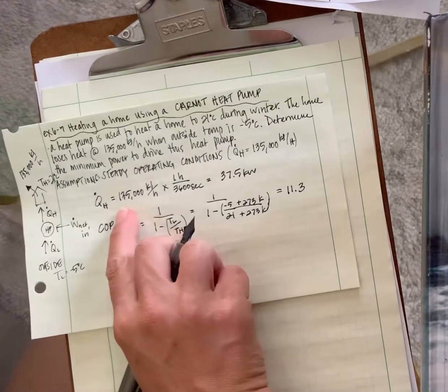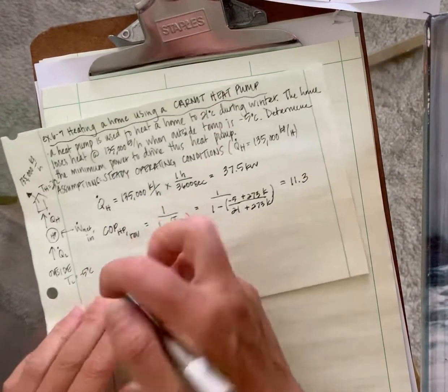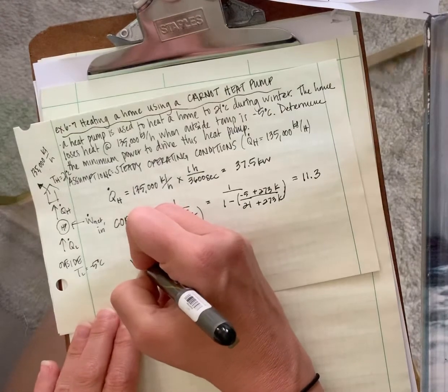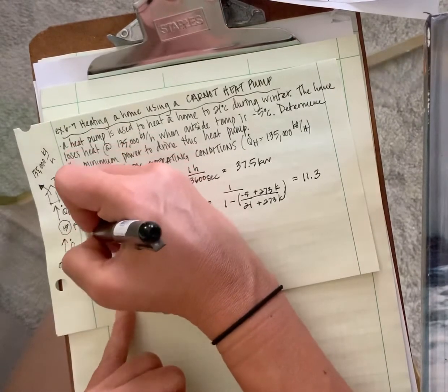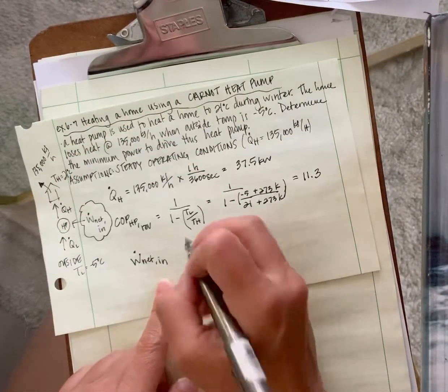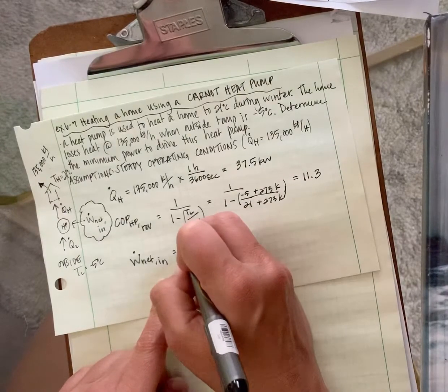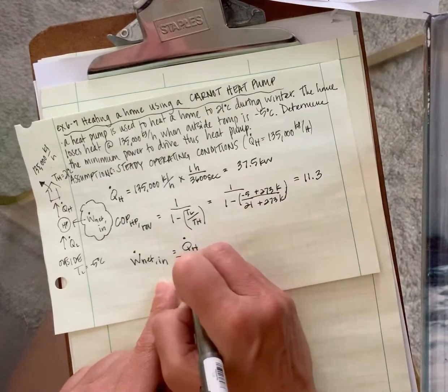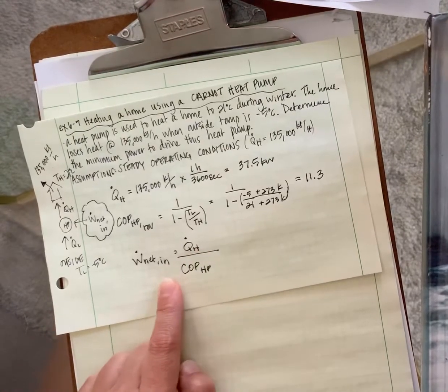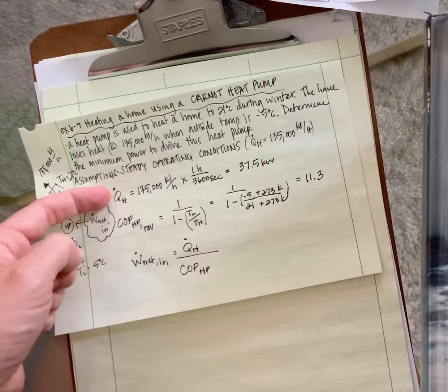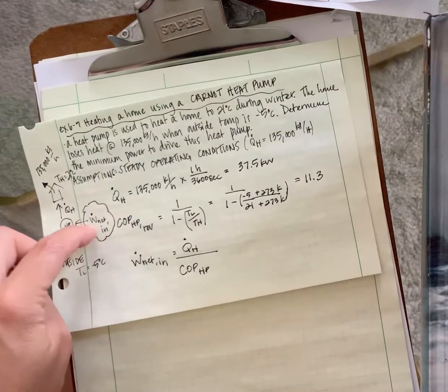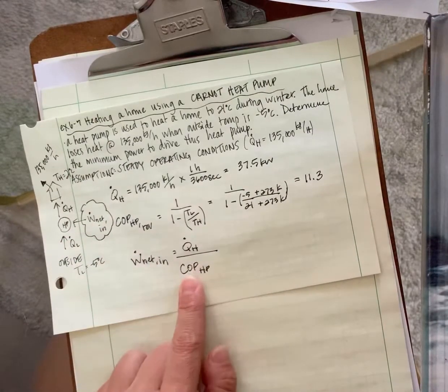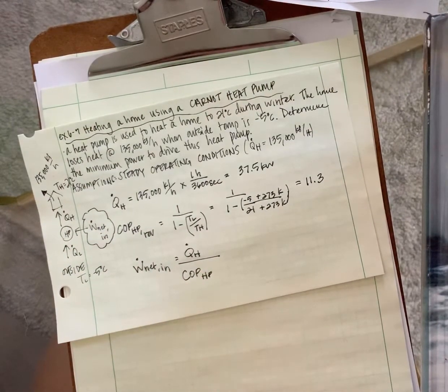Now I have my heat loss and my coefficient of performance, and I'm going to use my equation for work net in, which is what I'm solving for. My equation is the loss of heat divided by the coefficient of performance of my heat pump. I was given my heat loss, and I just solved for the coefficient of performance. If it helps you to start by thinking about what you're solving for, getting this equation, and then figuring out how to solve it, that's a totally fine way of working the problem. Figure out how it works for you.